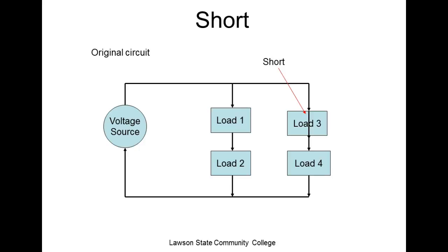What's the circuit breaker rated at? The circuit breaker on a 14 gauge wire in residential is rated at 15 amps, which is the current carrying capability of the conductor, not the load. You understand? So this is why they say don't run extension cords under carpets, because an extension cord is not designed to handle a lot of current. It has a pretty good deal of resistance. You could literally touch the two wires of a long extension cord together, and the wire has enough resistance not to pop the breaker.